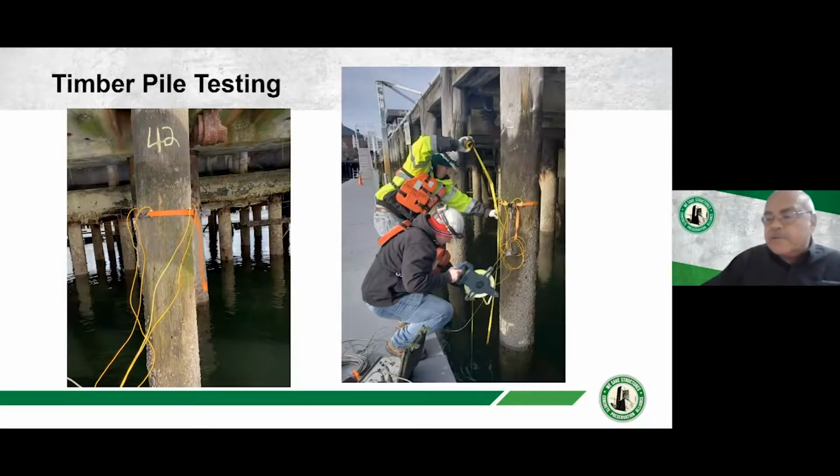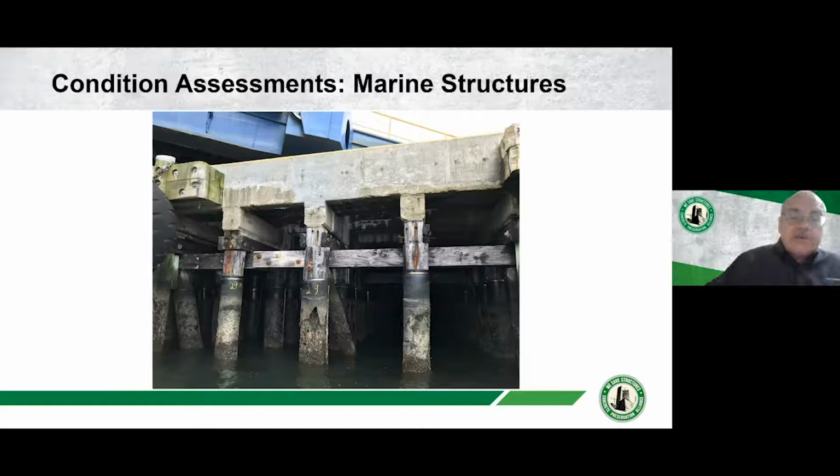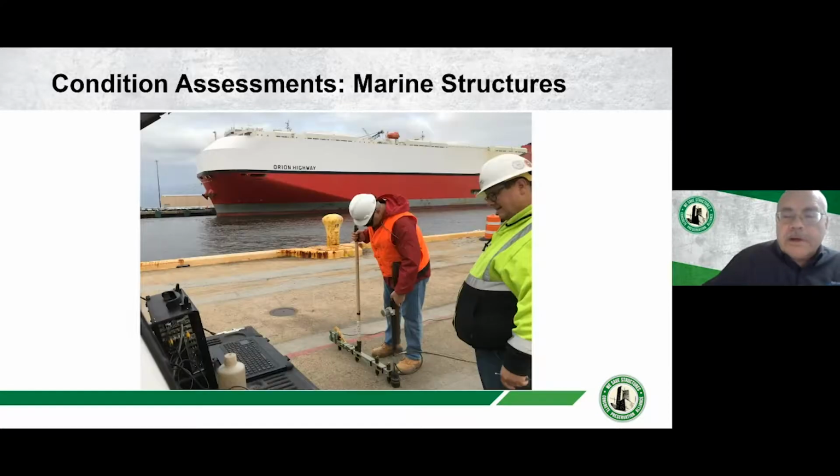Timber piles here, it's always important for us to measure where the mud line is, and if there's borings and we have an understanding of what the geologic conditions are, that's valuable as well. So trying to understand that. The marine structures, certainly piles as they go into the marine sediment, then there's concrete beams to be evaluated, and a concrete deck could easily be a concrete bridge structure there. We're up on the concrete deck here testing it.